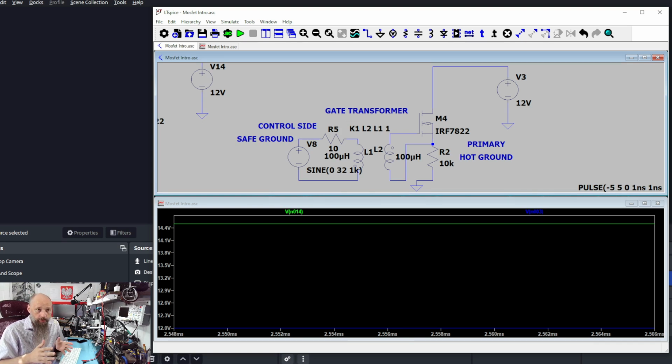And if you do hear those sounds, that's most likely damage to the coils, damage to the transformer. It's probably not going to be a transistor. However, it could happen that one of the transistors is not working, and that's what causes the sounds. But that would also result in voltages not being correct. So that should be easy to find. But you should not hear the transformer actually working in those power converters that work on 40 and above 40